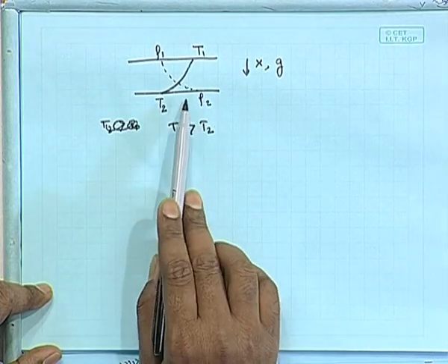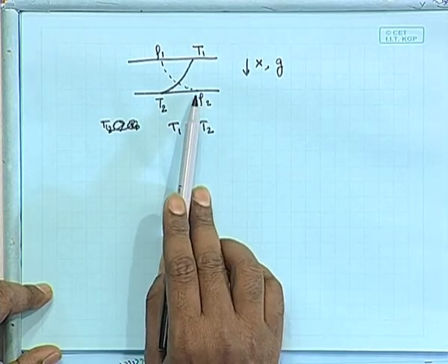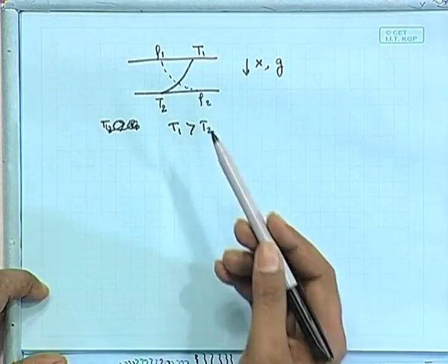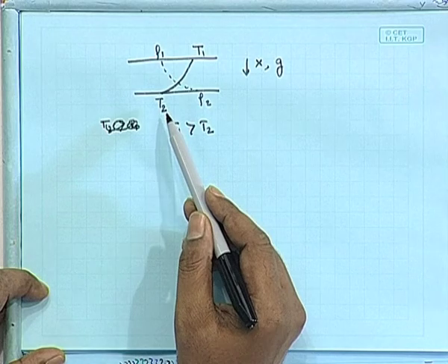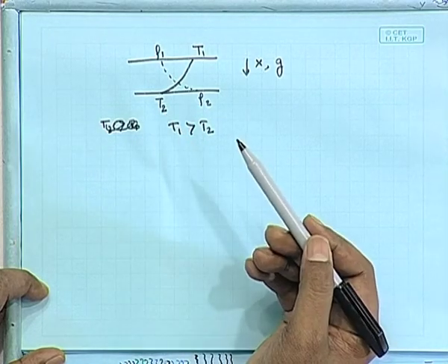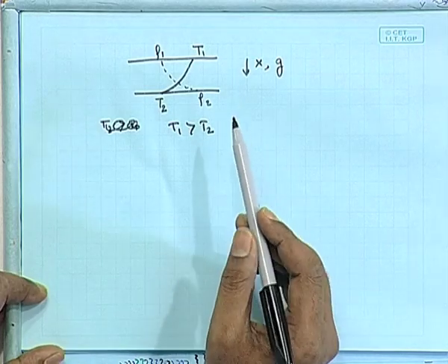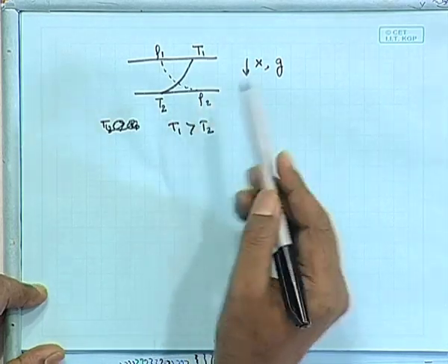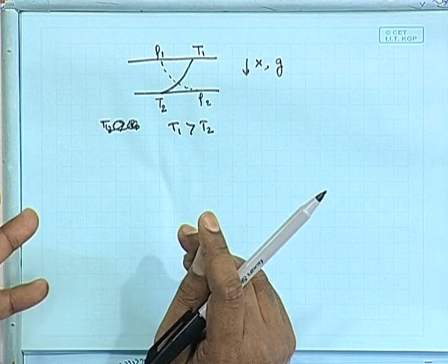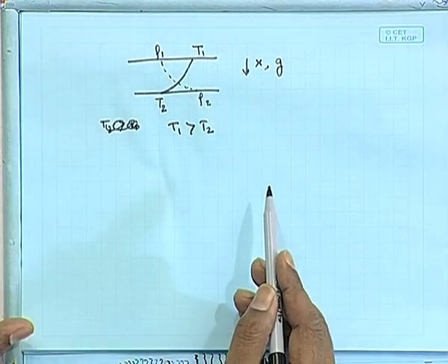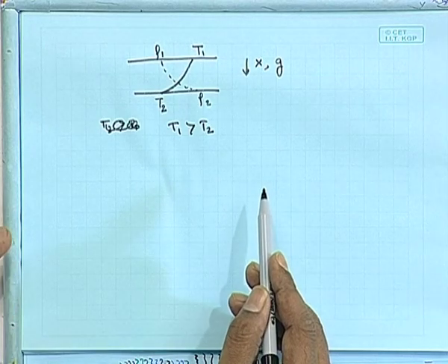The fluid adjacent to the lower plate will be heavier and will stay there, and its temperature is also less. So, there will be no setup of convection current. So, in this case, even if T1 is greater than T2, there will be transfer of heat from the bottom plate to the top plate, but not by natural convection, because you cannot set up a convection current here.